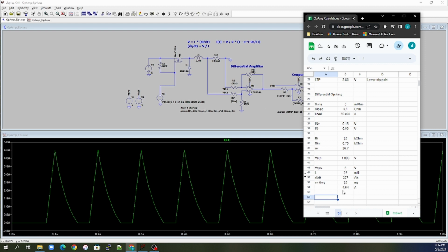And so our I max is just going to be equal to our voltage source divided by our sense resistor, which means our max current can get up to 1600 amps. So this is all theoretical, because you're more than likely not going to have an inductor on your board that has a saturation current or a capability of passing 1600 amps.